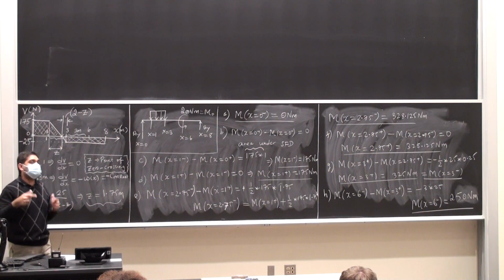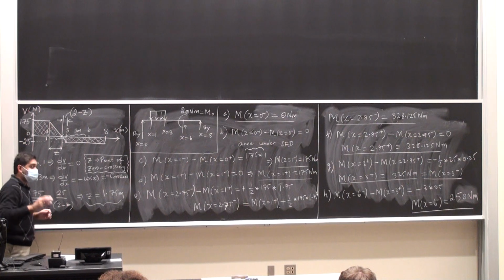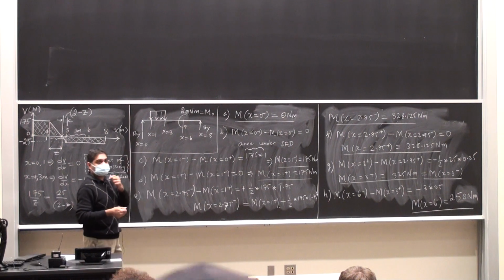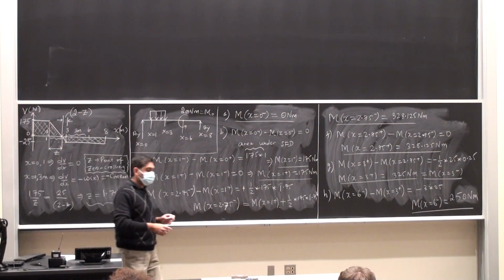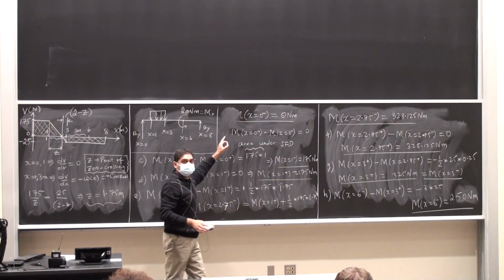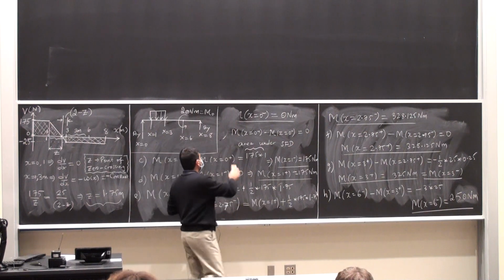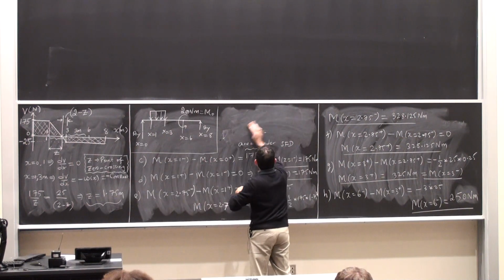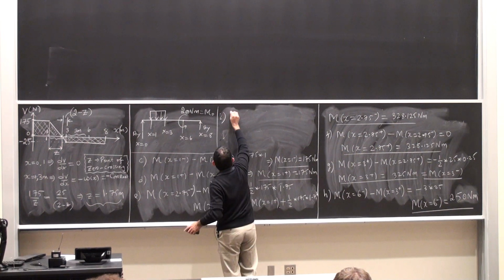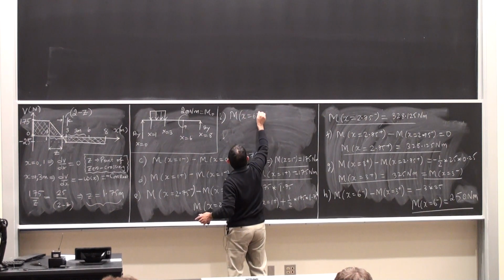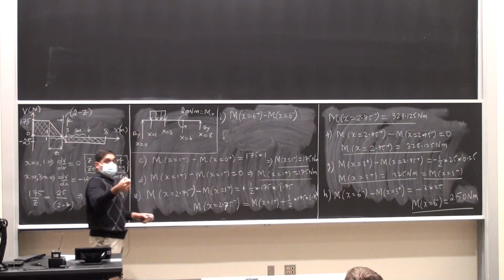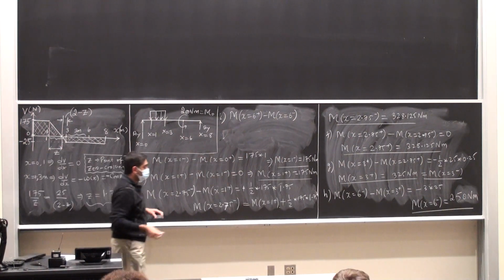I particularly mentioned that to you. It's an anomaly there. Every time you think counterclockwise, positive thing, good things are happening, that's not the case. In the bending moment diagram, a counterclockwise couple moment pulls it down. Okay? So I'm going to write that next. I'm going to get rid of the 0 guy here. So everybody good to go on this? M at 6 plus minus M at 6 minus is equal to minus M naught, which is minus 200.